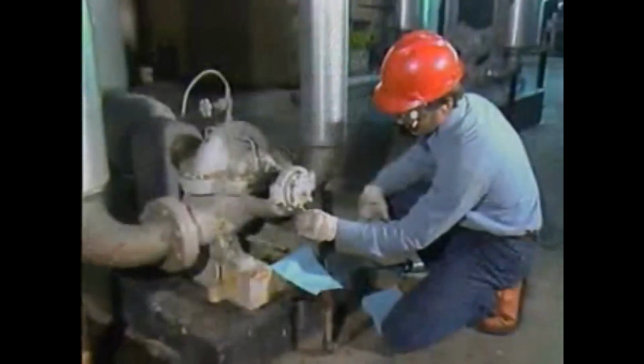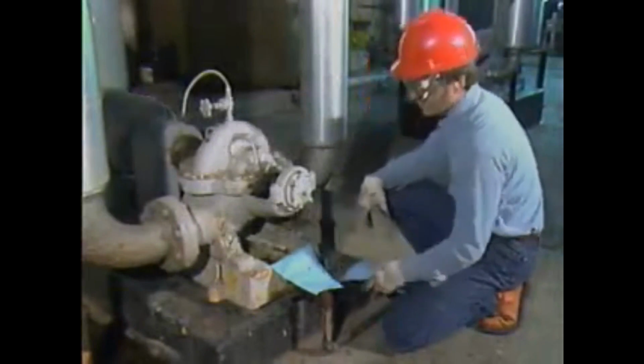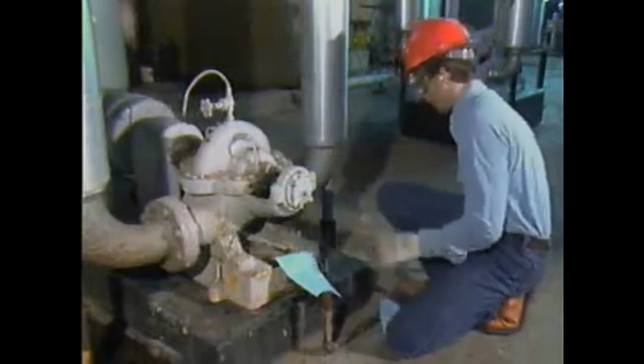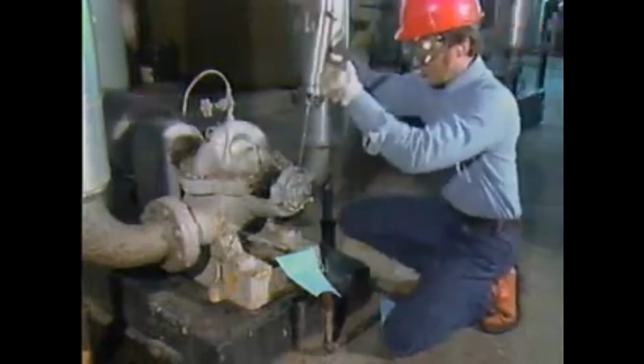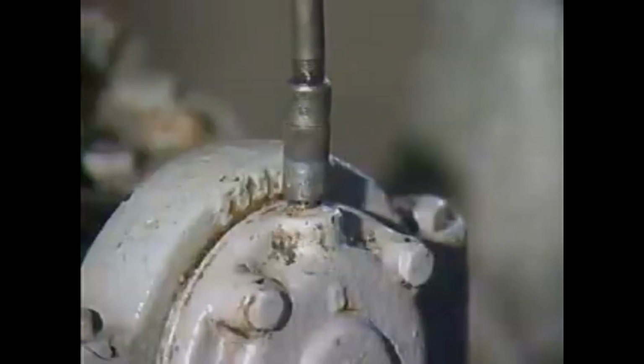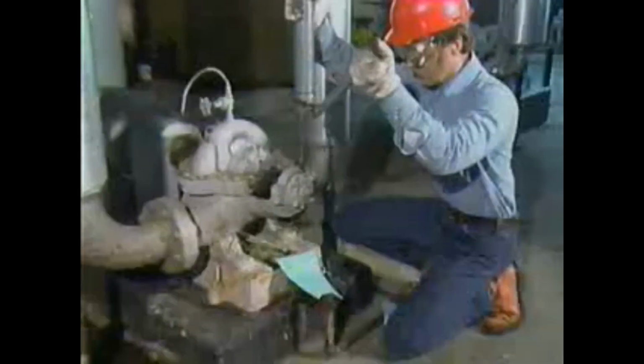To prepare to grease the bearing, remove the plug from the drain hole and wipe the grease fitting clean. Then connect the grease gun to the fitting and slowly add the specified amount of new grease while the machine is running. Don't overgrease the bearing. Typically, with a hand-operated grease gun, you should apply no more than 3 shots of grease at a time.